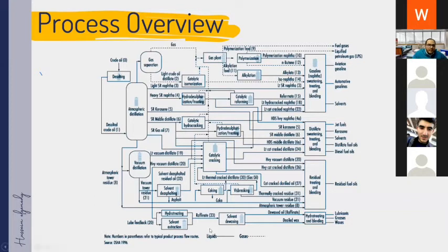All the cracking operations, such as hydrocracking, catalytic cracking or thermal cracking, have as their main purpose to crack the heavy components into light components, which are very valuable when it comes to the octane number and the gasoline blending and the other